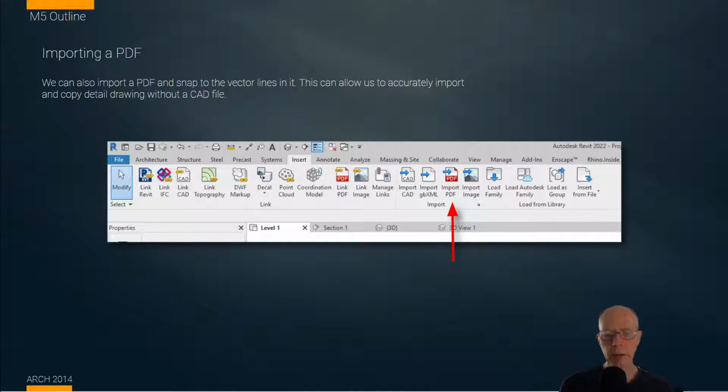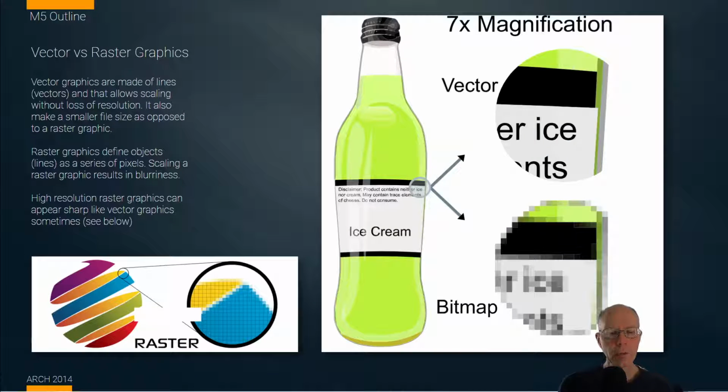And conversely, we can import PDFs into our software. So we can take rich, what I'll describe more in detail as the vector-based drawing, accurate CAD type drawings, two-dimensional though, into our software and use those as base layers for laying things out. Like somebody might provide a site survey that has important information in 2D, and we can then place our building on it and then locate things like trees or whatever very accurately because our PDF file is vector-based. So if you're confused about this idea of vector and raster graphics, bitmapped ideas, I hope this will kind of clear things up a little bit for you.